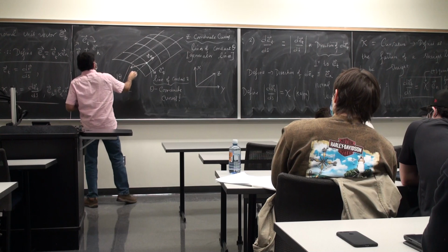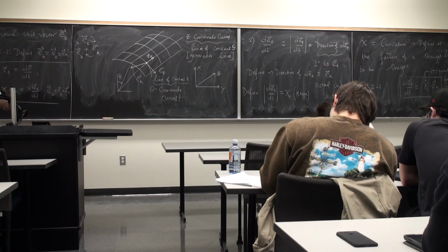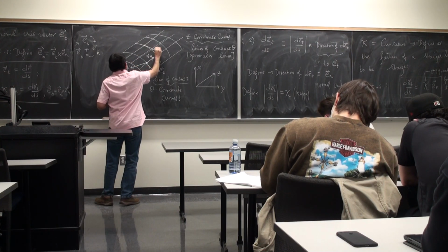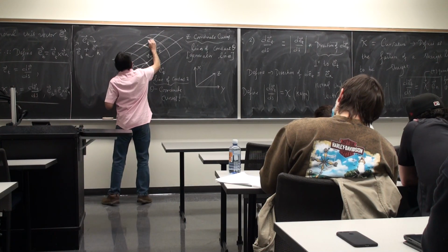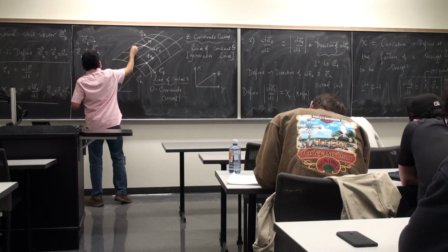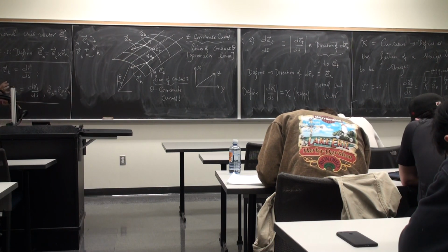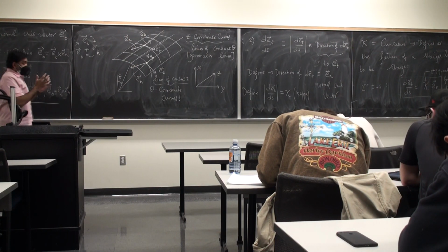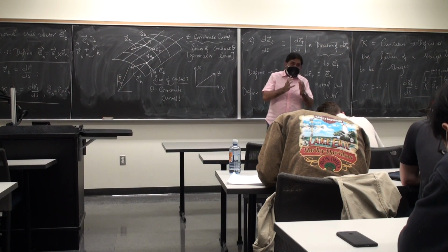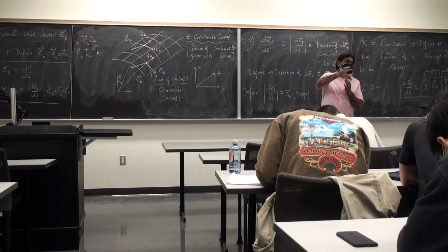So this is going to be my normal direction, and depending on where I am sitting, I have a different tangential direction, binormal, and normal direction. So this is a local coordinate system. At each and every point, the directionality of these need not be the same. They will be traveling along the surface of the shell.